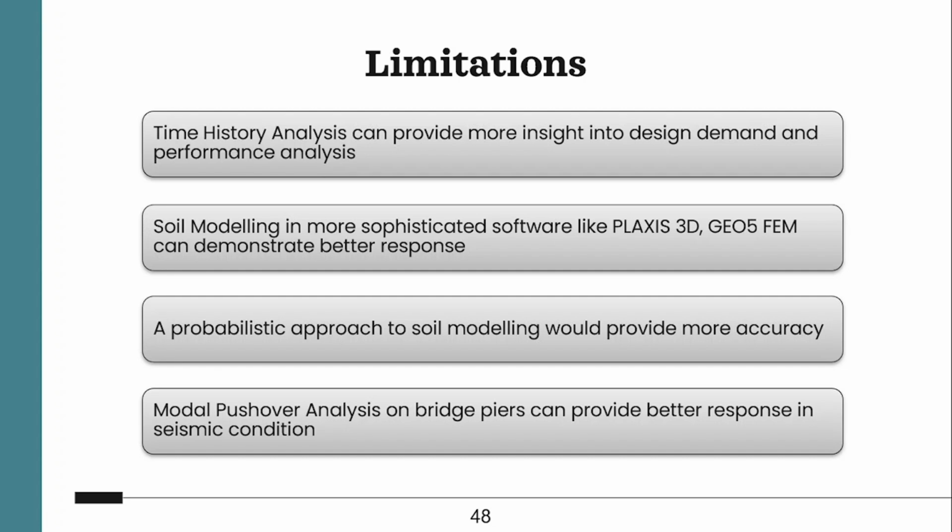As a result, I think we could have done a comparative analysis with the fixed base, and then checked what percentage of displacement the soil is taking, and that could lead to a better analysis. Also, time history analysis could have been used to provide more insight. Soil modeling could have been done in more sophisticated software.